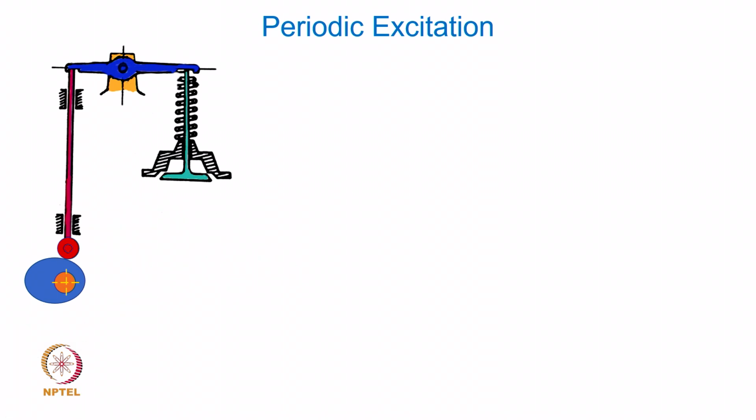That is one thing, and particularly in the context of this application, where the valve is supposed to open and just before the compression stroke should completely shut off, the motion of this follower is typically expected to have a different kind of cam profile.